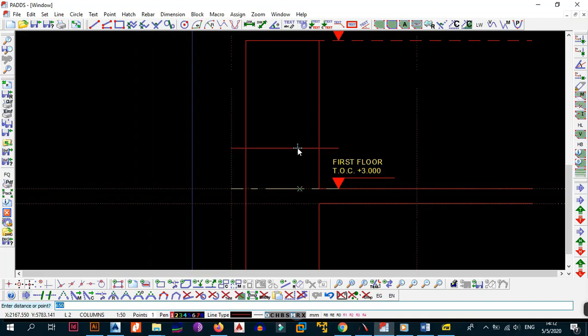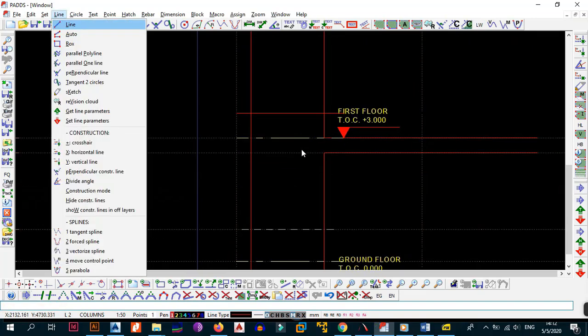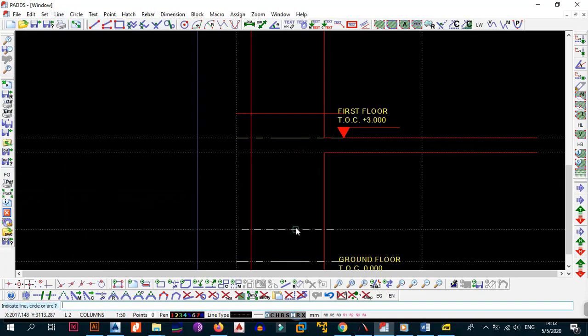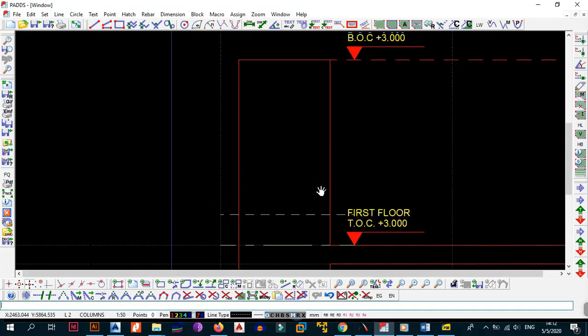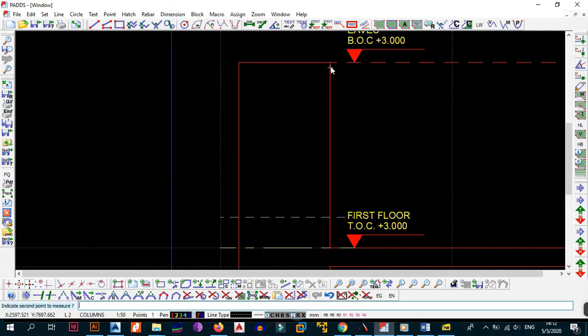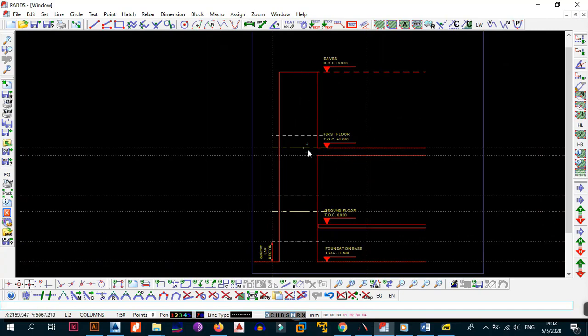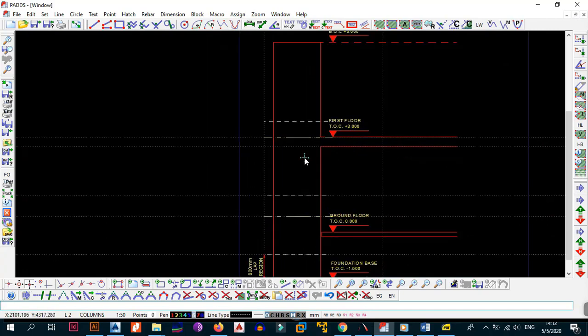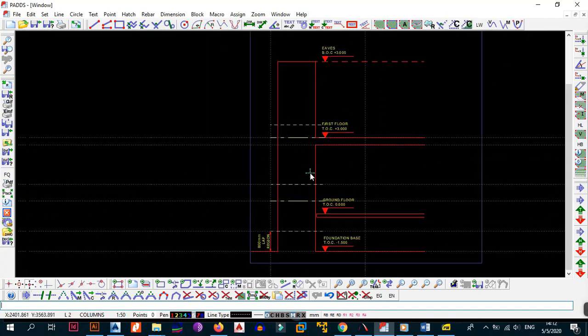So LP by 500 to show you the lap, and then LG to get the parameters of the line, then LS, so this is where next lap will be, and the rest they're just going to cast from there to there. It's 2.5, so there's no need. This is where the column will end. So this is how we're determining the heights where they're going to cast to, and the heights where they're going to lap their bars at, or the regions where they need to lap their bars.